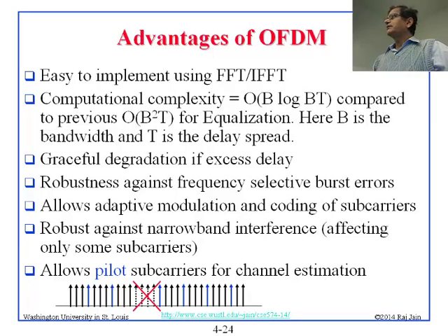Again, this is the same thing as frequency selective. Narrow band interference means somebody else is transmitting, but they are not using the whole band. They are using some small part of the band. We call that narrow band. If they are using the whole band, that is wide band. Now there are two terms we use: noise and interference. Noise generally is due to sources that are not expected, that is just noise, right?